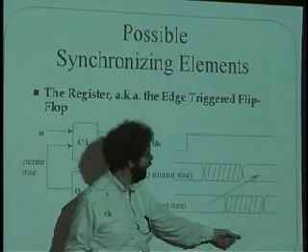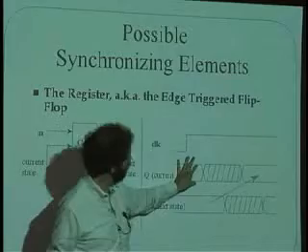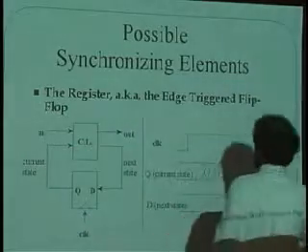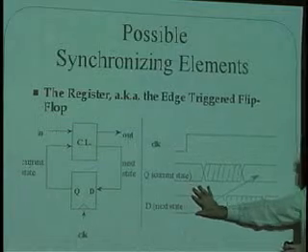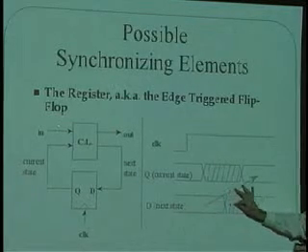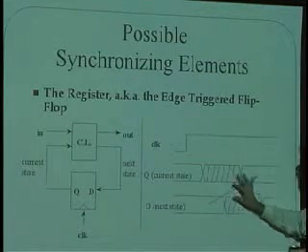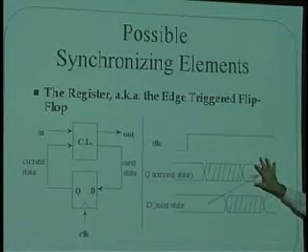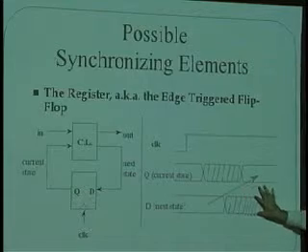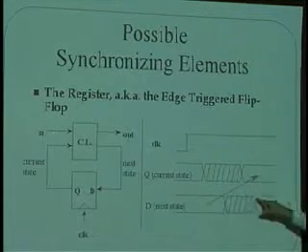Time is going by on the x-axis, and so Q goes from having its old value being erased. A short time later, D goes from the old next state to being some intermediate thing that we're not sure of. And then finally, when this thing settles on what the next state is going to be, a short time after that, that combination of logic produces the next state.